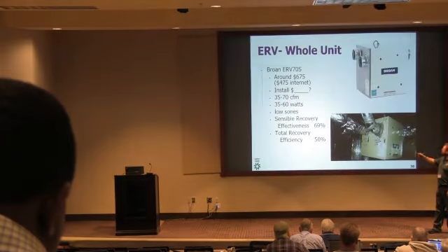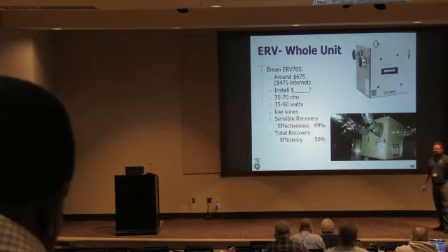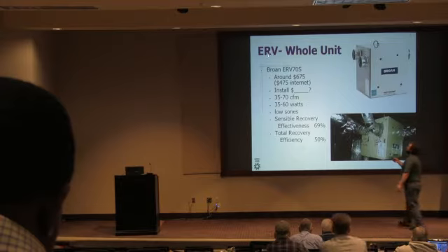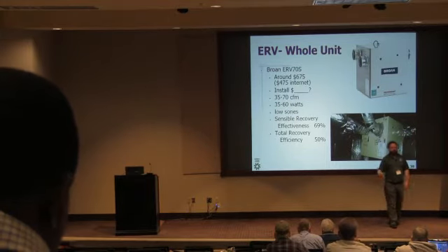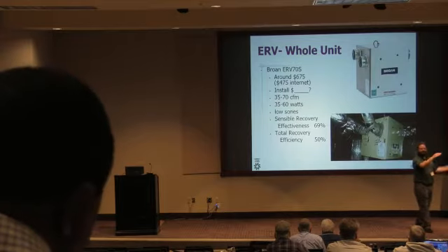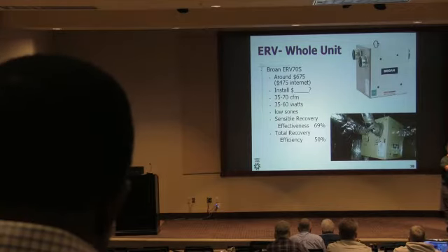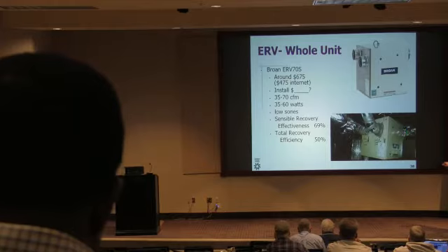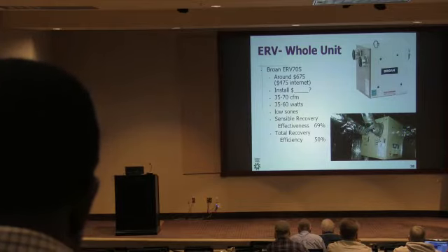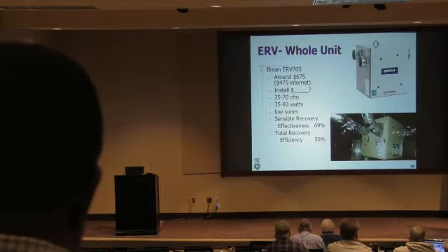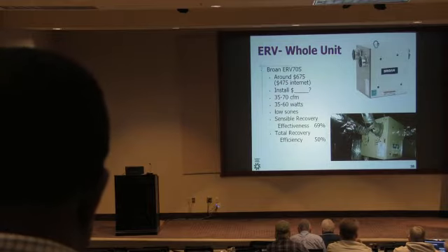Okay, here's another one. Somebody brought up an ERV, an energy recovery ventilator. This is a piece of equipment that will blow air out of the house and bring air into the house, and it will use basically a heat exchanger inside here to precondition the incoming airstream with the outgoing airstream. They say it's free preconditioning, but you're running a fan, so it's not completely free, but you're not running a coil.